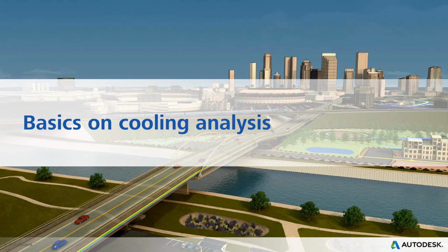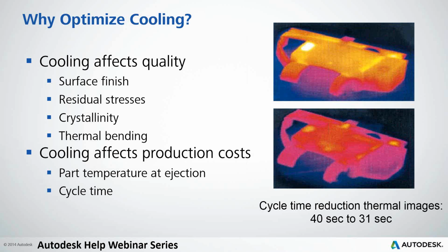Okay, so basics on cooling analysis. Why do we want to optimize the cooling? There are mainly two different goals for optimizing the cooling. The first of them is the quality of the part. Depending on the time that we are cooling a part inside of the tool, we have different surface finishes.